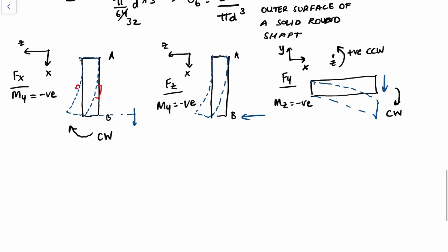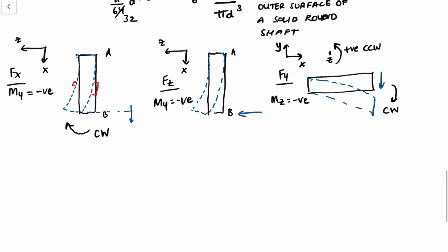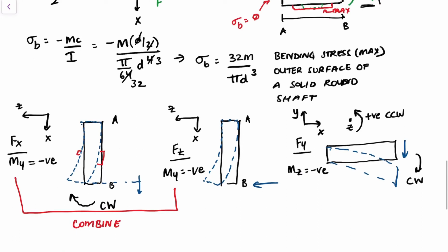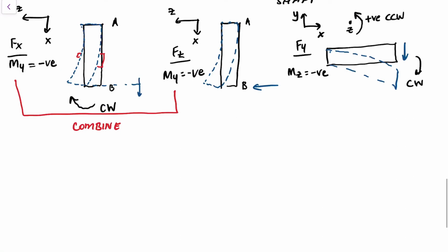So now what we can do is combine these two first, and then take the sum of squares in both the planes because we know what the y is, what the z is, and then we can solve for the moment. And again, you will have to find out what the resultant moment is on a given cross section before you calculate the stress. So what else do we need? We know the force, so this is Fx, and it's being applied at a moment arm,